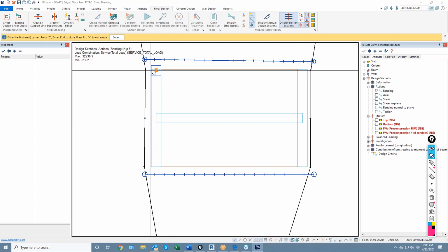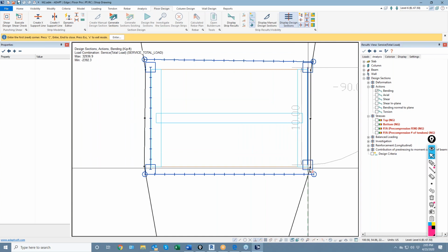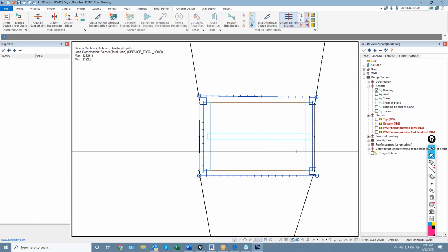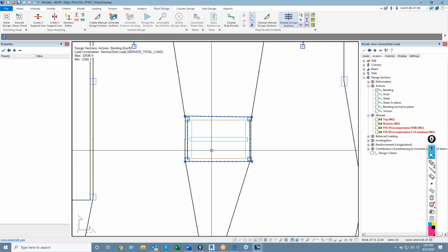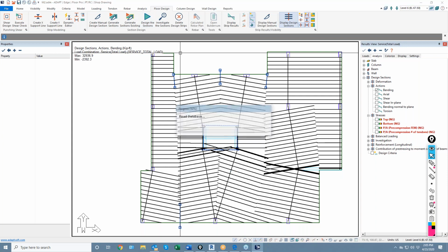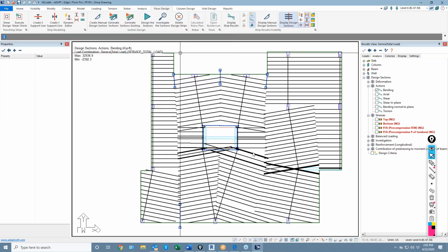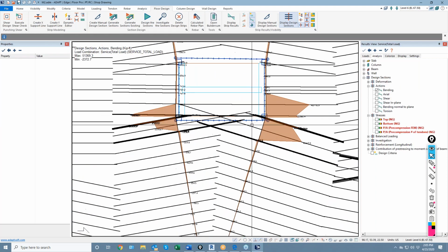So let's create a splitter here. Another thing we could do is use a wall boundary tool in the program, but I'll just do it through use of the splitters for sake of time. I have probably another 10 minutes or so. I know I've gone over time, so I appreciate everyone sticking with me that's still here. All right, let's go back and design the cuts again, see if that resolves that issue. It's just an integration problem with the nodes crossing those walls.